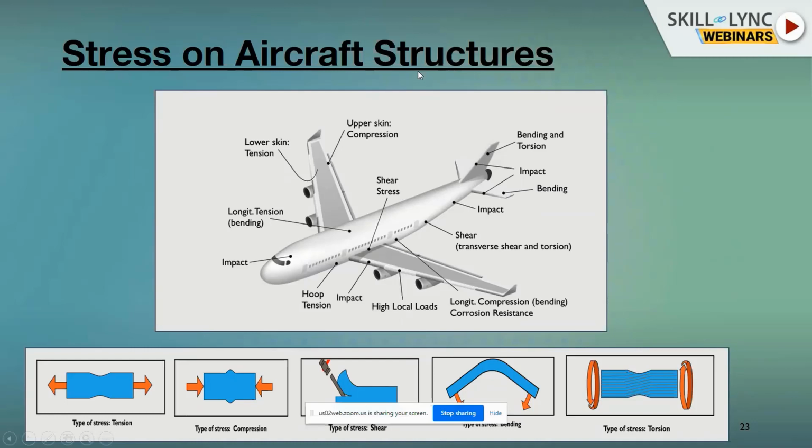If you are going to be an aircraft structures engineer, then the basic thing you need to know is the basic formula, P over A plus MC over I: axial and bending loads. The third is torsional, but axial and bending is like, each and every component will go through axial and bending.